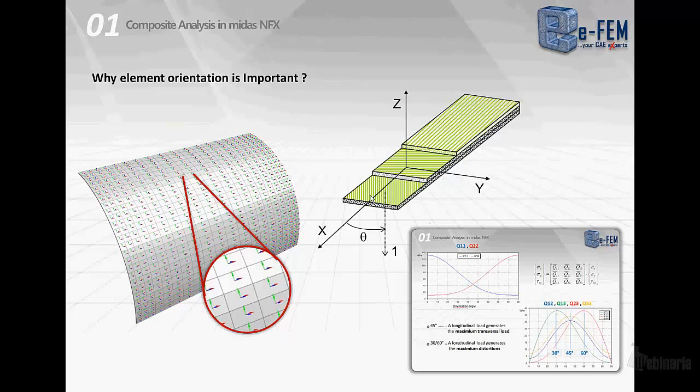Sabrina, I would like to start my second presentation with this image, because your presentation and your example remind me that we didn't talk too much about orientation. As I've said before, it is really important to define the orientation of the material in the lamination and in the stacking sequence, and also for the single lamina, because the stiffness properties are really different at different angles of orientation.